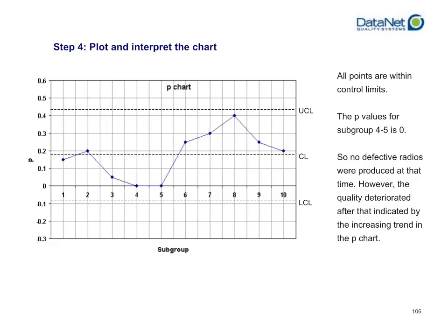So we've gone ahead and plotted the solution, or the graphing of the control chart. Now we can't absolutely know what was going on here, but we can make some inferences from what we see. It is your job as a quality expert, a quality engineer, to go in and actually begin to investigate what you see here. The lower control limit was less than 0, meaning we would expect that getting no defects is within historical norms, or is normally distributed data. Your upper control limit is at around 40%.